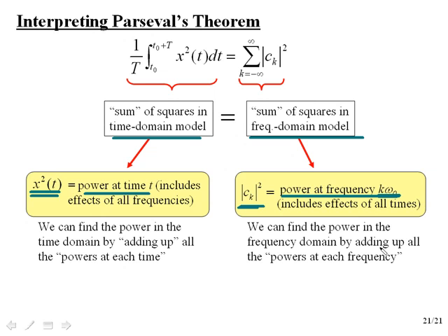So what this allows us to do is to see where in frequency the power is concentrated. And in practice, that's extremely important. If we're creating a signal and we need to, for example, transmit that signal over the radio airwaves, the FCC controls how much power we can have in certain bands and how much power is allowed to slop over into other bands. So, for example, a radio transmitter would be under FCC regulations.